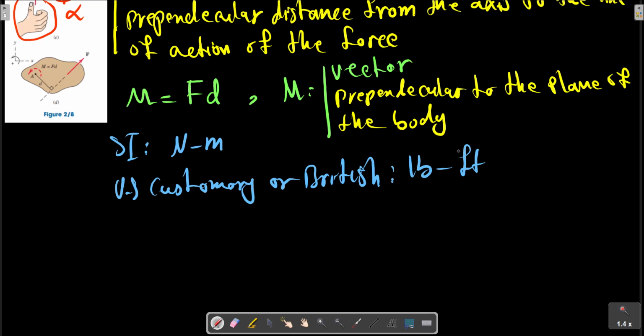When dealing with forces which all act in a given plane, we customarily speak of the moment about a point. By this we mean the moment with respect to an axis normal to the plane and passing through the point. Thus, the moment of force F about point A, for example in this picture, has the magnitude of F D and is counterclockwise.